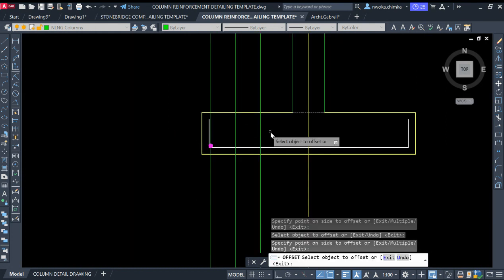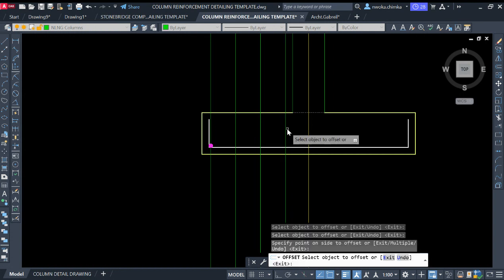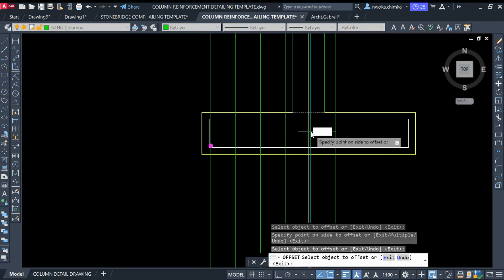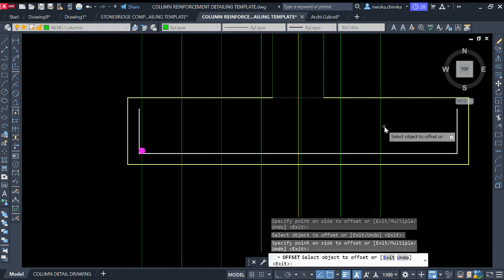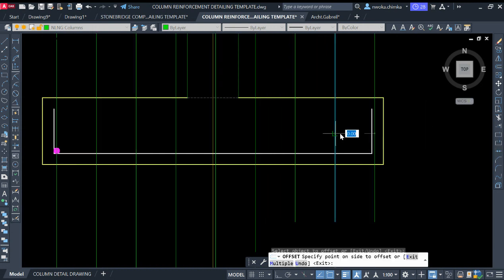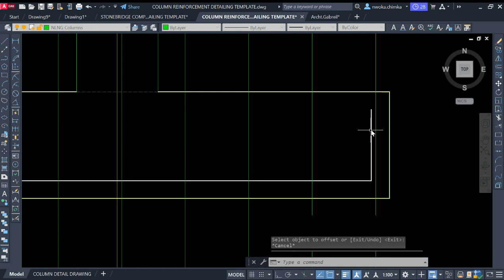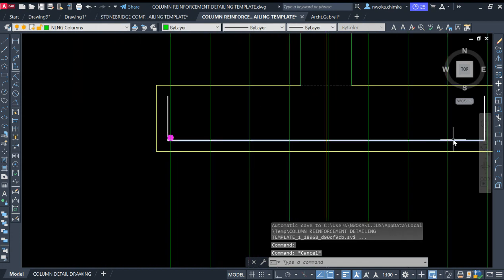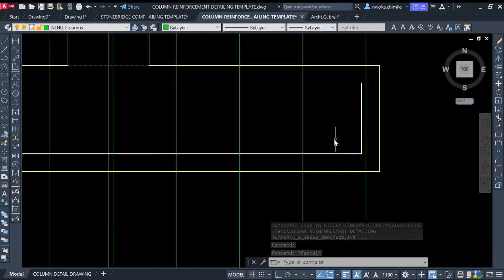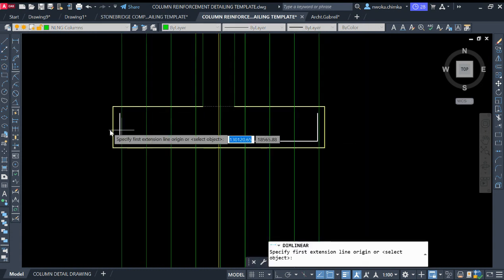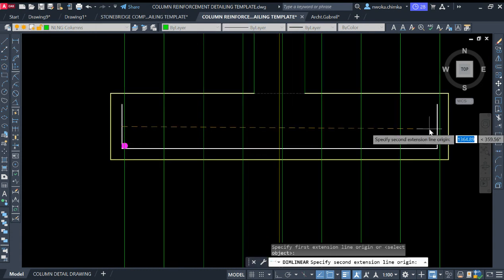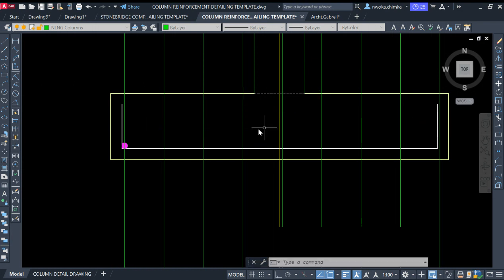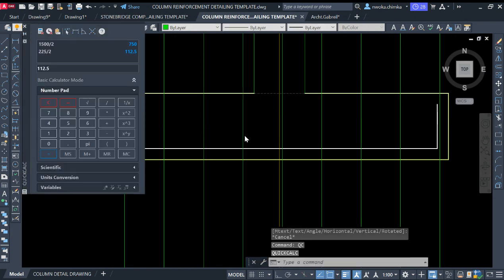You can see that click on this again, and again, and again, and then the last one will just fall in here. If it didn't fall in, because we used to have some kind of spacing, if you divide this now by 175, if you take this right now, 1400 divided by the spacing 175, you see that you're going to have a decimal value.